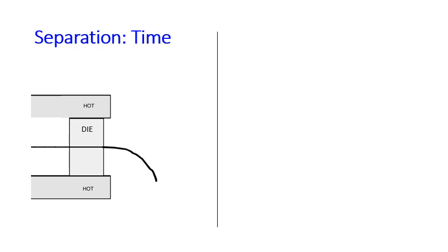During the process, when we pull the wire, the die must be hot such that it can remove the excess of the enamel and then produce accurate size of the wire. However, if this process stops for something, the hot die will bake the enamel and it will destroy the wire.